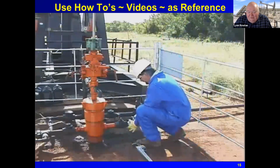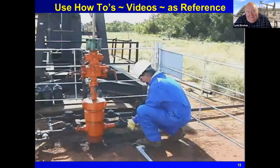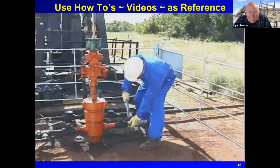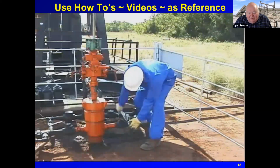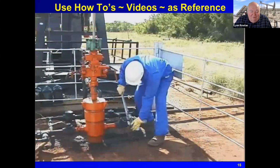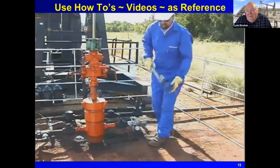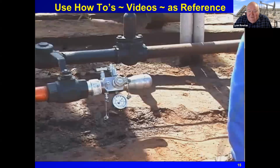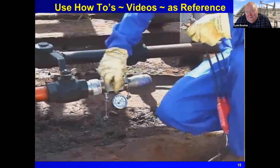He's going to attach the gas gun to the well and make 4.5 complete turns to make a safe connection. And he will check the pressure on this well before he attaches the gun, and make sure that the well pressure doesn't exceed the working pressure of the gun, 1500 psi. And then he'll be able to, when he charges the gun, fire a shot.